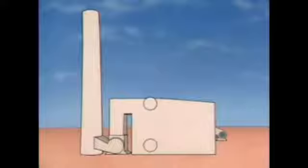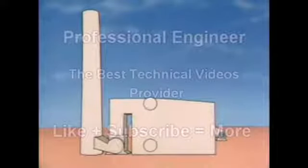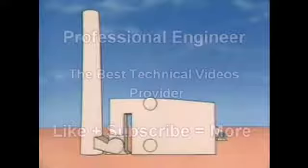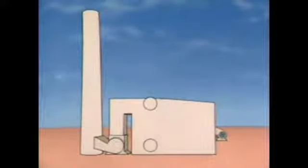It's important to maintain the proper fuel-to-air ratio to avoid combustion problems. For example, if the boiler is not getting enough air, some of the fuel entering the boiler won't burn. Instead, it may get carried out with the combustion gases and wasted. In some cases, unburned fuel could build up in the boiler. This buildup could cause an explosion if the fuel were ignited.